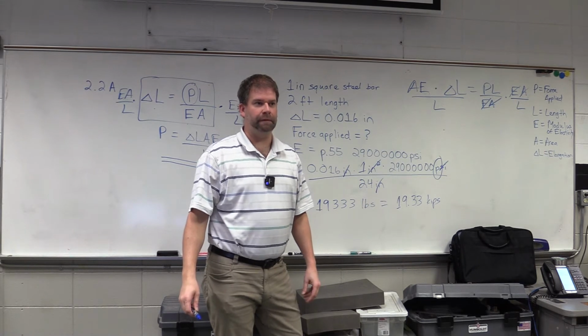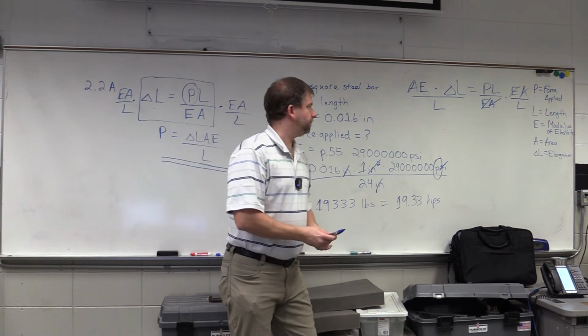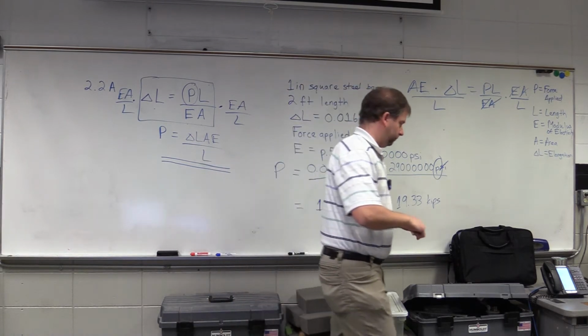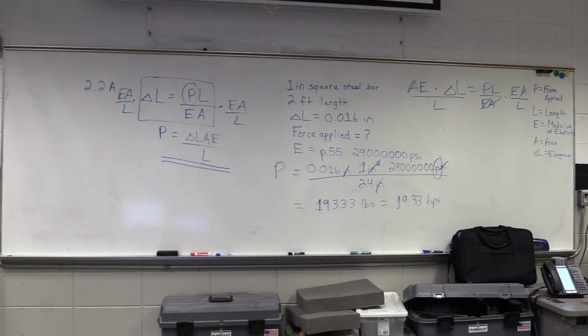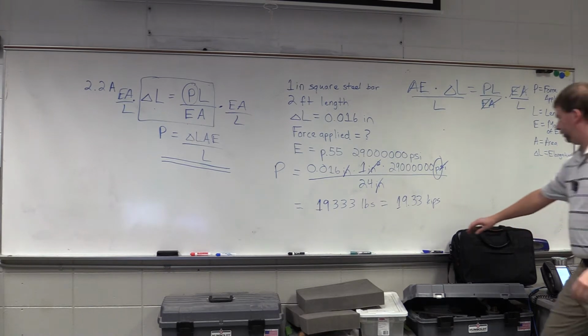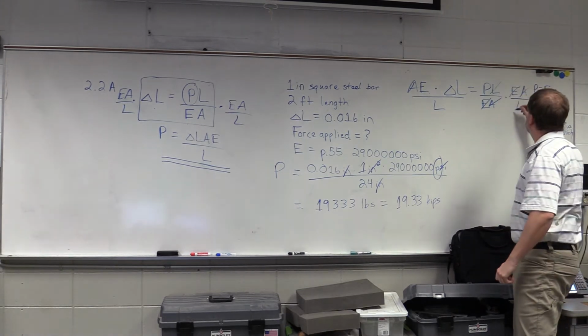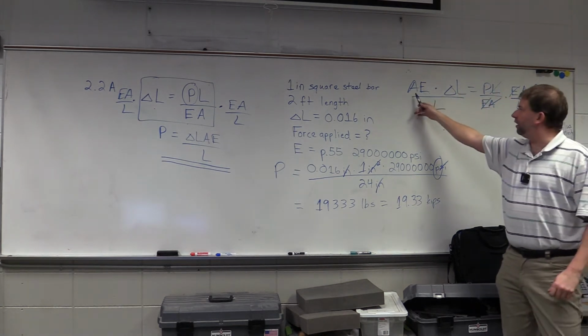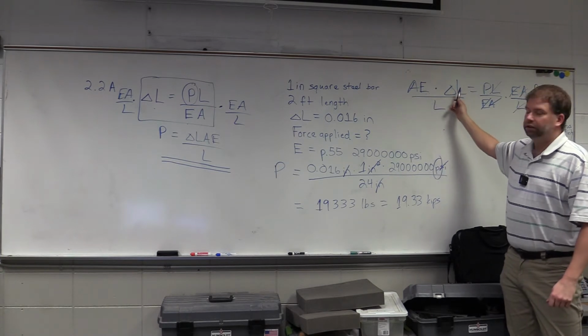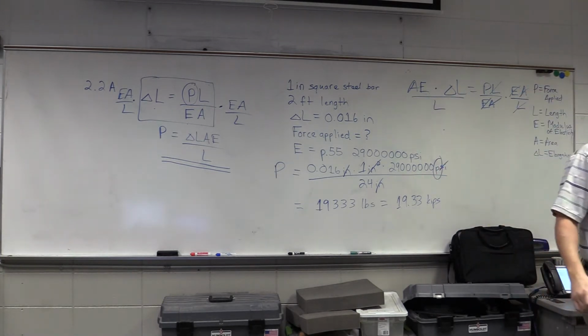Everybody come along? Good? Right, we can cross off our L term. So force applied equals the area times the modulus of elasticity times the change in length divided by the initial length. Okay?